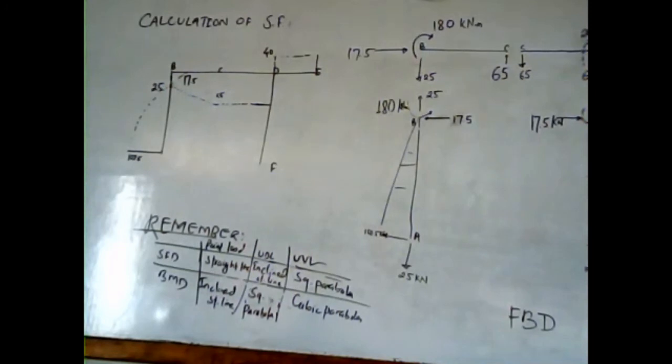This shear force at point A is acting upward. We need to know that left up, right down is positive, and the vice versa is negative. So the left 102.5 in section AB is in the upward direction, so it is positive 102.5. Likewise, at point B, 17.5 is acting upward. Left up, right down is positive, so this must be a negative one. So we have written negative 17.5 on the negative side.